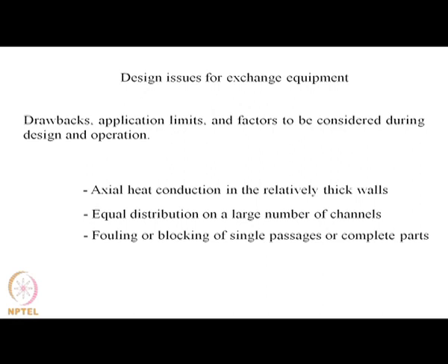Another important thing that I haven't spoken about before is fouling or blocking of a single passage or complete parts. It is not possible in most cases to clean a microchannel once it gets fouled or blocked by the presence of suspended particles. So, these are some of the issues that one has to keep in mind during design and operation.